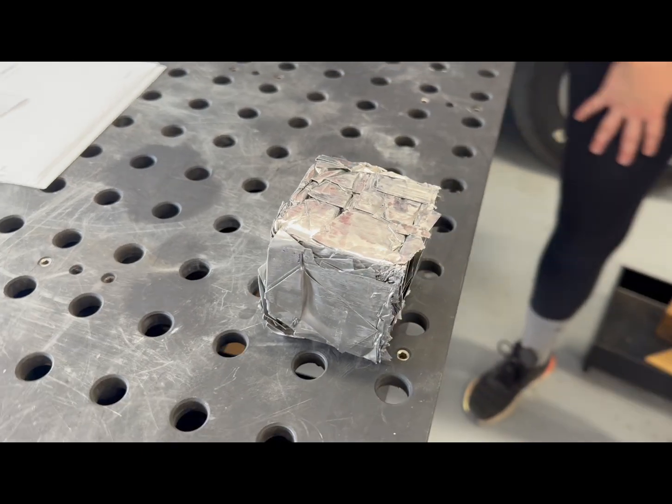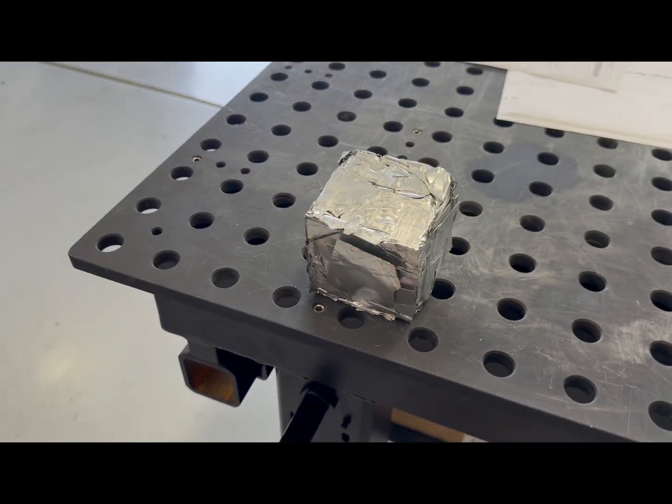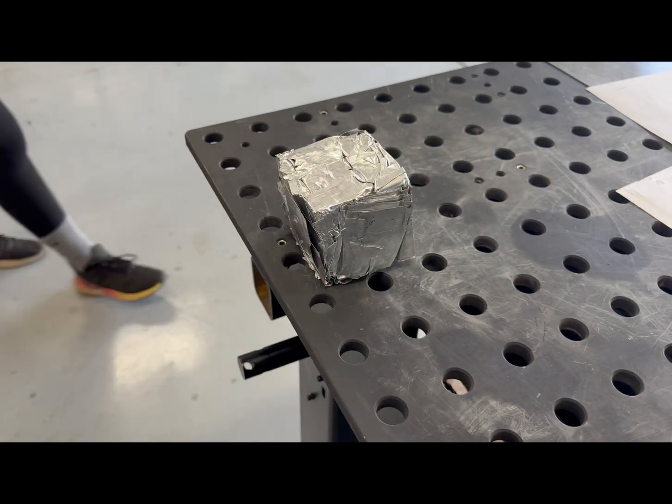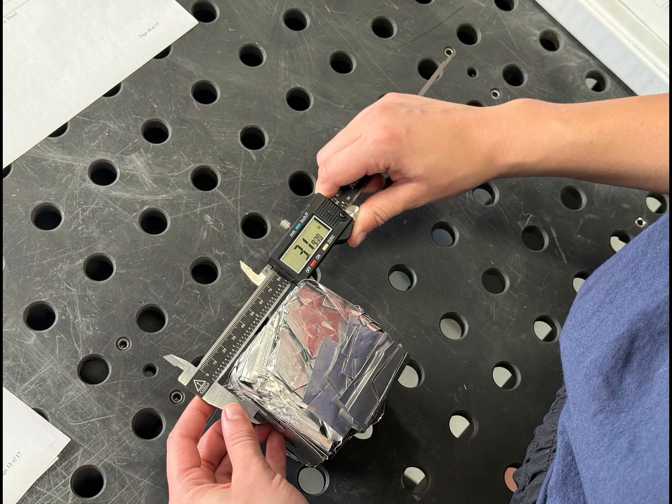So here are the results of our system. As you can see, we were able to successfully produce a uniform bale with consistent geometry. The material is much more tightly packed compared to the loose scrap, which significantly reduced air gaps. This improvement in packing is largely due to the pre-processing and the two-stage compression process, which work together to increase overall bale density. By increasing density, we expect to see improvements in remelting efficiency, including higher material yield, reduced dross formation, and lower energy required per melt. Overall, these results support our original hypothesis that pre-processing and staged compression can have a meaningful impact on aluminum recycling performance.